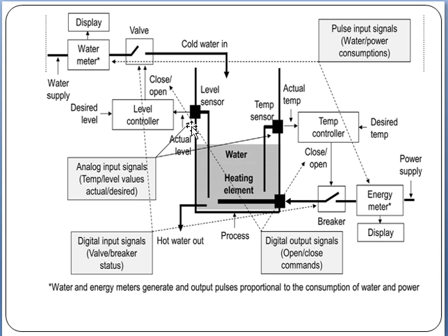The level controller has already been given a set point. When the actual level is less than the desired level, the level controller generates a signal to open the valve. So the valve is open and cold water enters the tank. Second condition, when the actual level is higher than the desired level, then the level controller sends the signal to the valve. It means the valve is now closed, and no water is coming inside the tank.